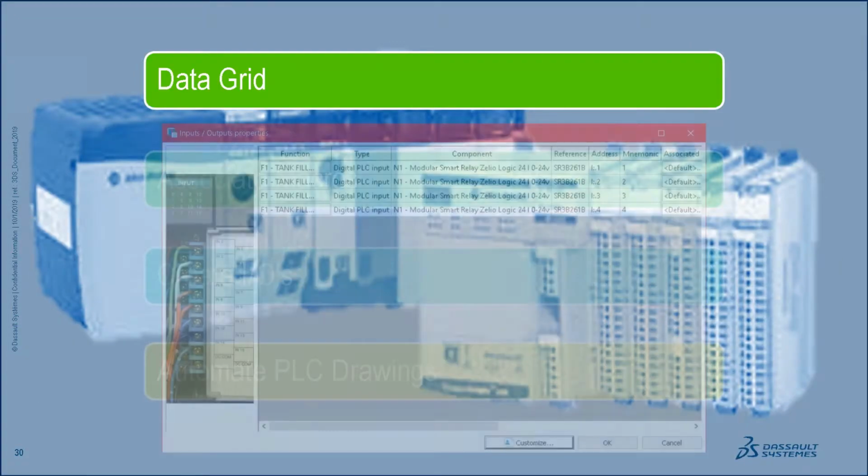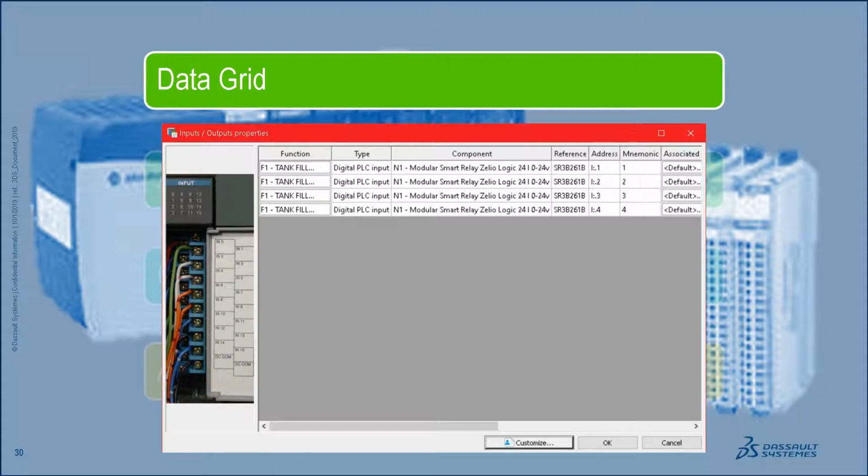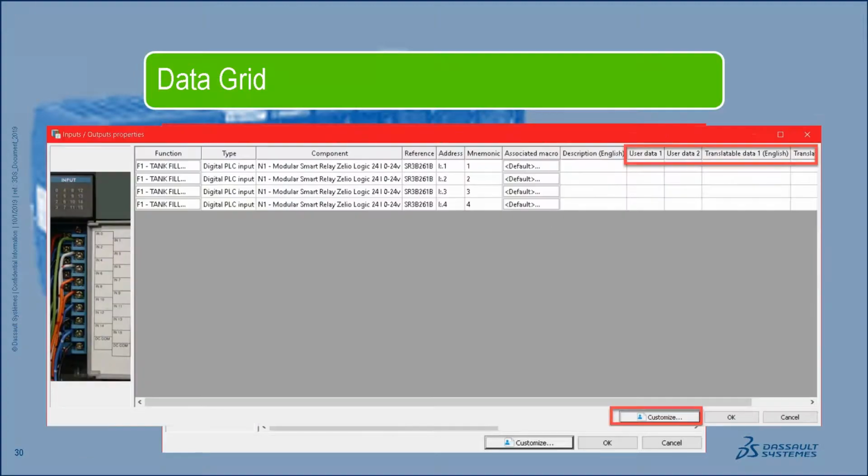After that, we can start working with another feature within our PLC manager, just a continuation of more tools within your tool bag, one of those being the data grid. The data grid is a way for us to manipulate information within the PLC manager in a more user-friendly manner. It takes us into cells and rows like Excel, and in fact you can copy and paste things. So if you had description information or some type of manufacturer's data or PLC data contained within a spreadsheet, simple copy and pasting of cells within these will allow you to quickly get the data and reuse that. Now, there are a bunch of other options that are available within this dialog box.